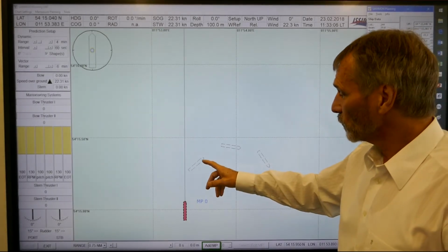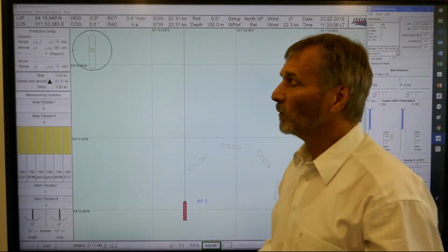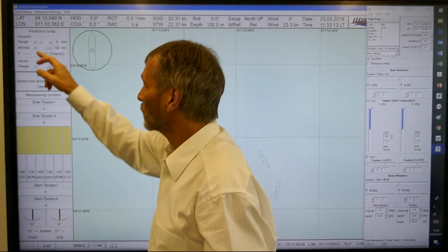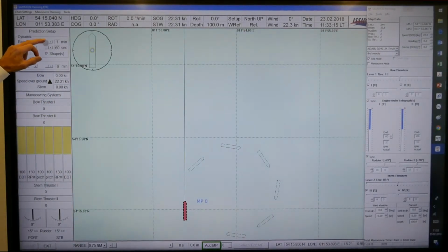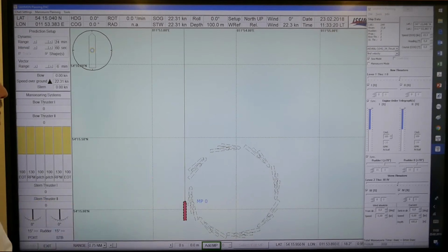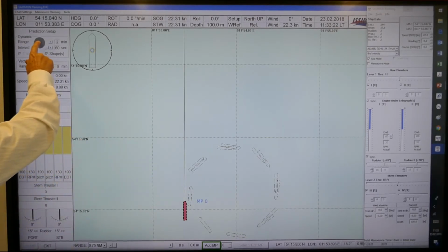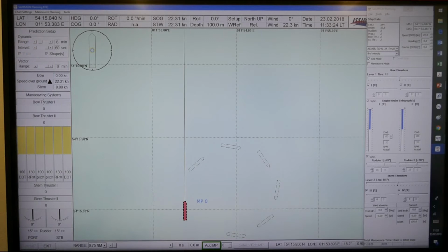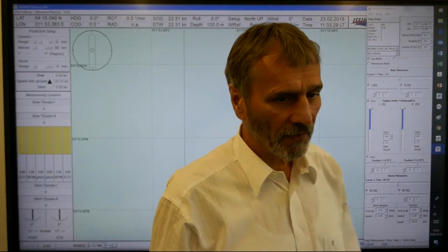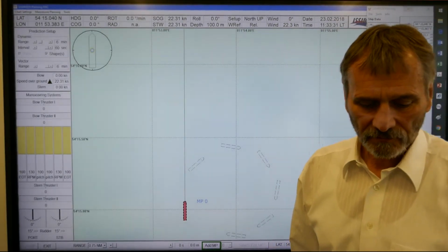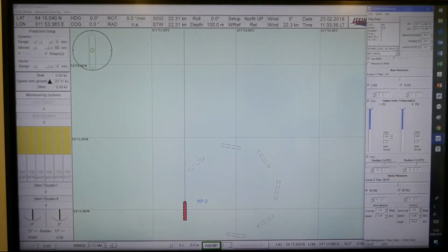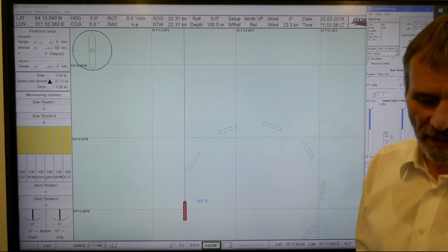So now it's 4 minutes of ship shapes. This can be enhanced if I do it with 6, or for the maximum 24 minutes ahead, then you see the change of the ship. So maybe we should put it to 6 minutes. So you see immediately the effect of these maneuvers. And you can also change the rudder, for instance, to 10 degrees, and you immediately see the results of this one.